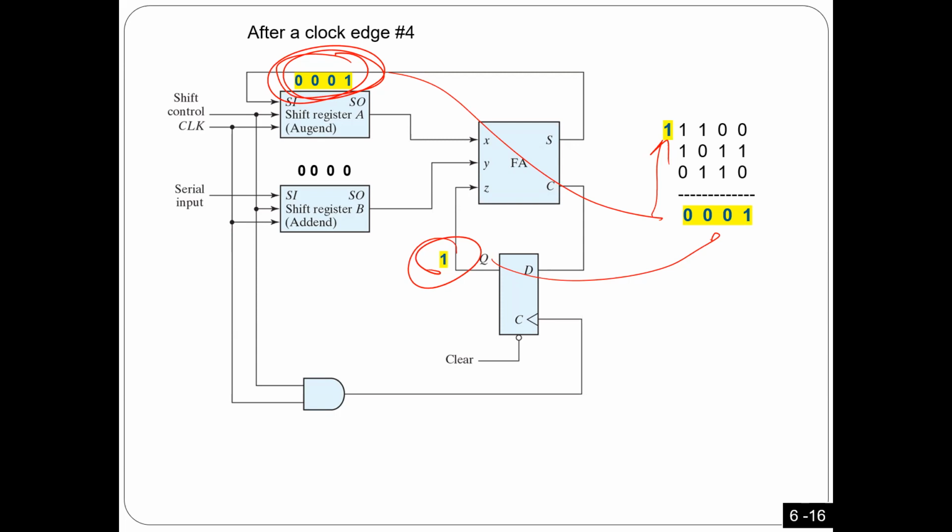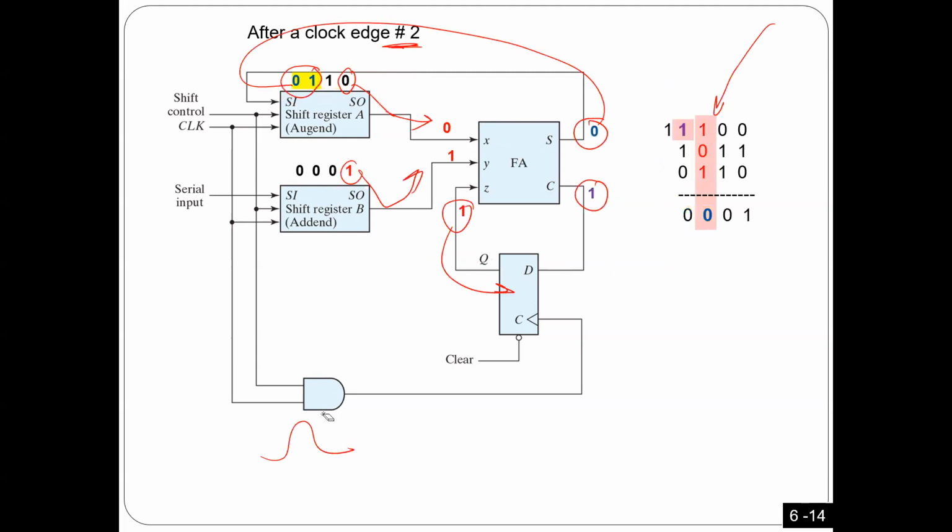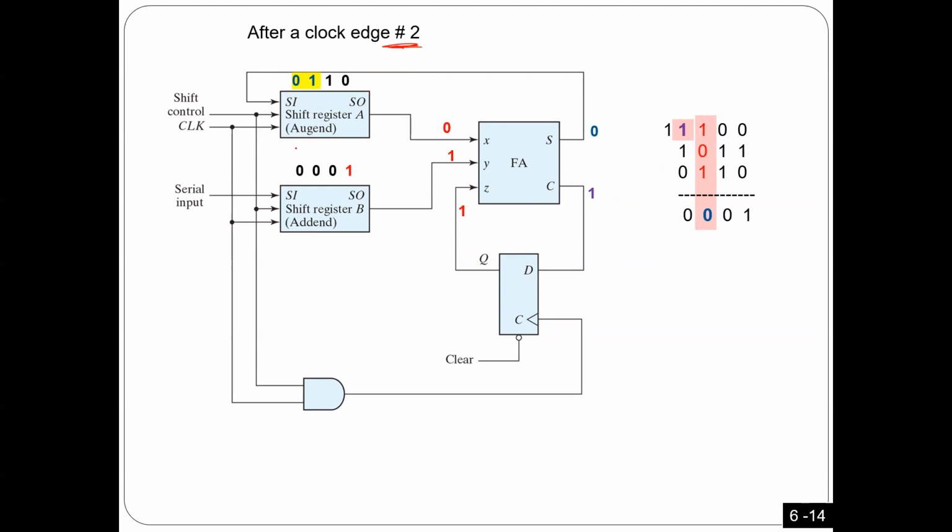Because every clock you shift 1 bit, you do the addition, you store the carry here because you need the carry next time, okay? And then you need to store the result somewhere, you store it here, okay? Anyway, one interesting thing here I did not explain yet. As you see from the conclusion here, every clock you shift to the right here, every clock you shift to the right, and the result from here, I insert it here, okay?